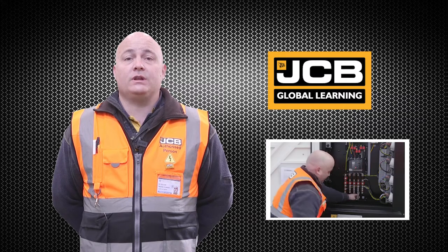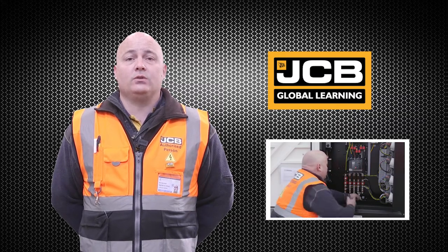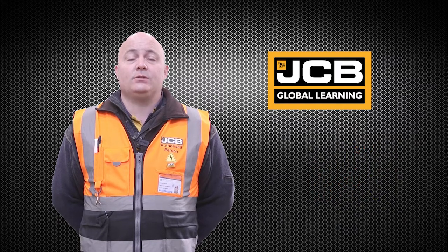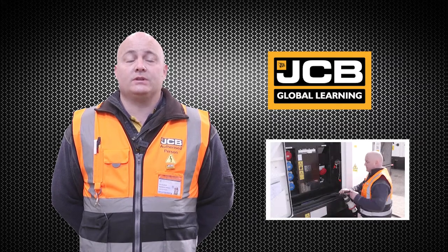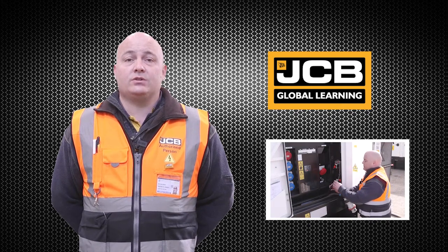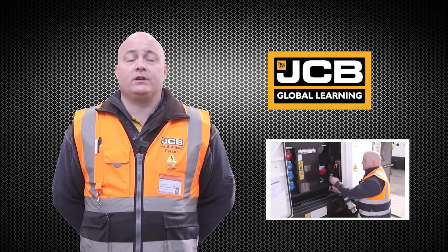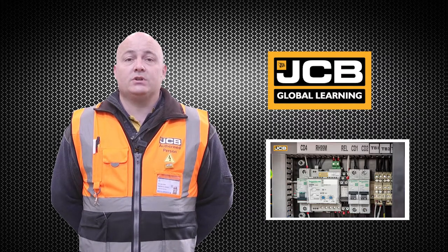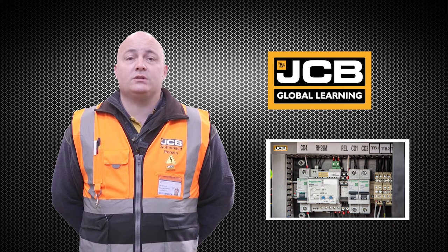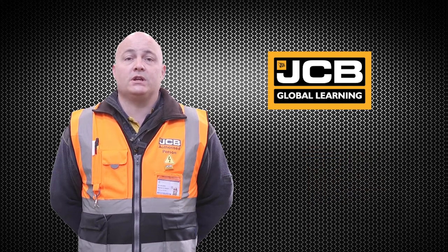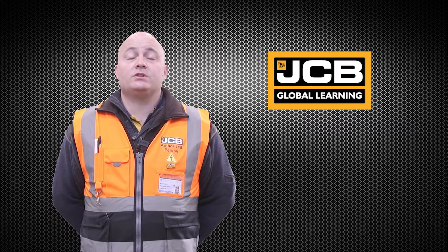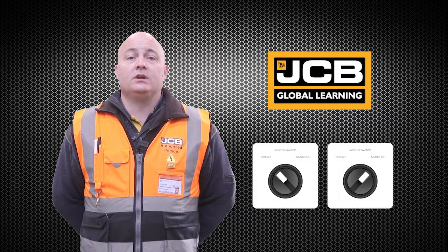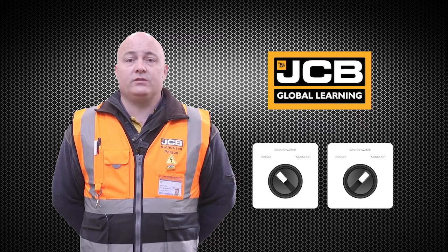In there we looked at the bus connection, which connects the power between all the generators and can also connect to the load. We looked at how to connect to the load through the plugs on the front of the set. The MSC connection, which is the data connection between all the generators within the synchronized sets. The earth leakage relay position needs to be set to the off position to prevent unnecessary trips when using synchronized generators. The resistor switch needs to be in the end set position for the end generators and the middle set position for the middle generators.